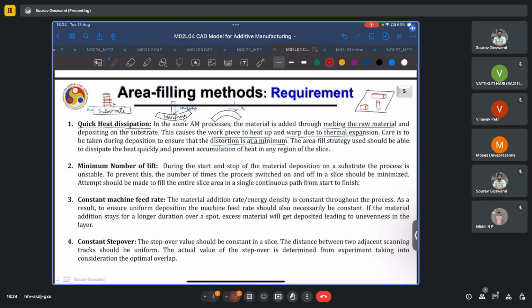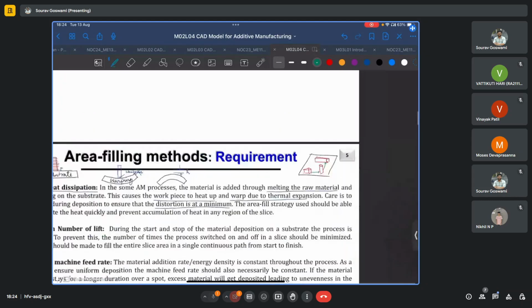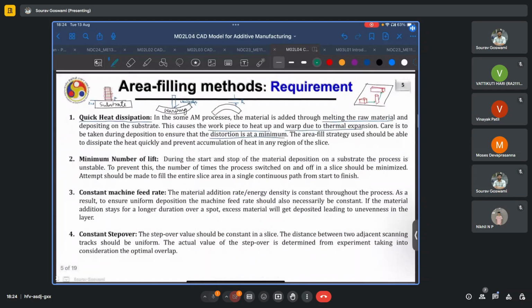So it cannot print continuously. Once it is done depositing a layer of one material, it has to go to the other object and then deposit there. So the travels in between these objects and then travel back in the next layer will involve no deposition and only free movement of the head.